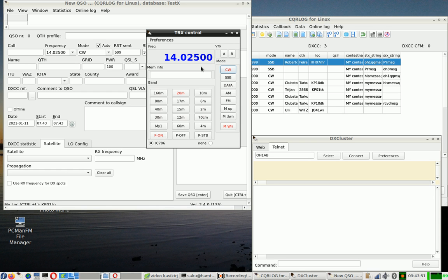You don't have to think what the next transmission frequency would be. Cqrlog will give you a random frequency to try. And of course, if I press now Control 1, it was the 1000 Hertz, 1 kilohertz split, and so on. Unfortunately, you cannot see it from the display here, but it's visible at the rig side if the rig supports XIT, the Delta TX system.